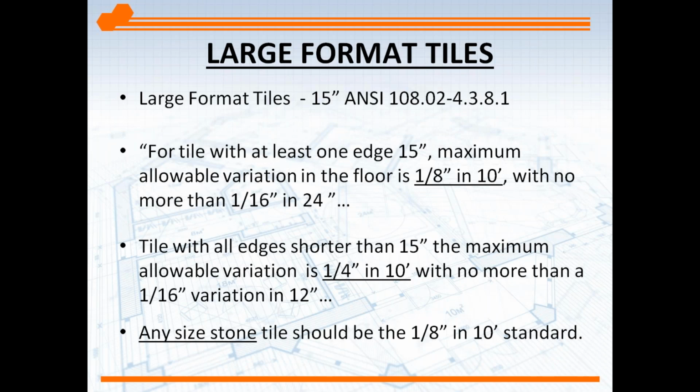Traditional tile, and what the standard has always been in the past before these large format took over, is 1/4 in 10, the next paragraph down. So any tile that is smaller than 15 inches still goes by that guideline of 1/4 in 10 with no more than a 16th in 12.